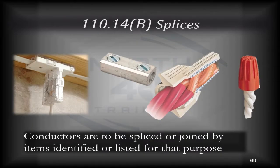When it comes to splices, 110.14(B), conductors are to be spliced or joined, and they're supposed to be joined or spliced by devices that are listed for that purpose.